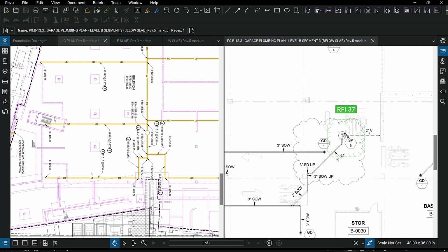And the sump pit is basically like a storm drain or a sewer. It's a series of precast, usually like 48-inch precast pipe set on top of each other. Anyway, there's a pit right here, a collection location for all the water. So the water's coming in here, gonna land in this pit. The water from this side's coming down this trench over here and then going in.